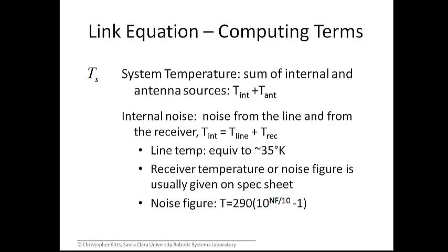So some of this noise comes internally, and in particular the receiver itself. That's probably our primary piece of equipment that's doing the reception job, and it has an equivalent noise temperature. Now, this is not the temperature we think of if we put our hand on it and it feels hot. This is a different temperature. This is a temperature associated with the noise that it generates in the radio frequency range, in the microwave range.